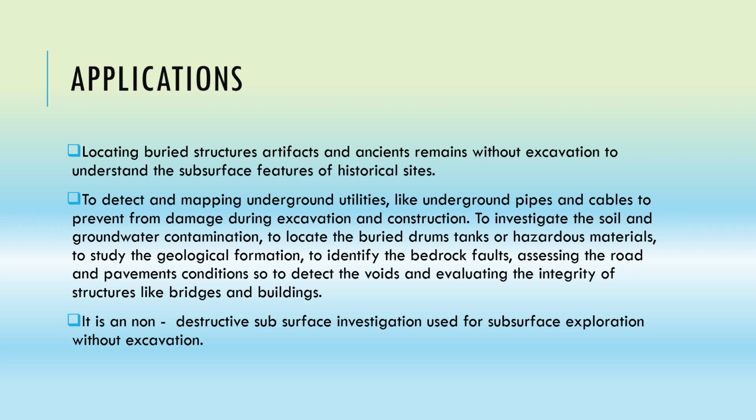So it is a non-destructive subsurface investigation used for subsurface exploration without excavation, because for a large scale of excavation we need a large amount of money, and then we have to do the processing, and we do not know how far it has been present. If you are going to dig out or excavate a large area, then we need a large amount of money. We do not know at which depth it is present. So in such cases, you can use GPR as a source for digging out and excavating without spending money on that.